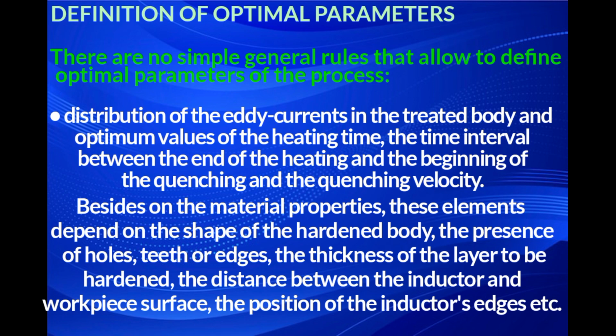If we talk about optimal parameters for this induction heat treatment process, there are no simple general rules that allow us to define optimal parameters of this process. These include the distribution of the eddy current in the treated body and the optimum values of the heating time, the time interval between the end of the heating and the beginning of the quenching, and the quenching velocity.